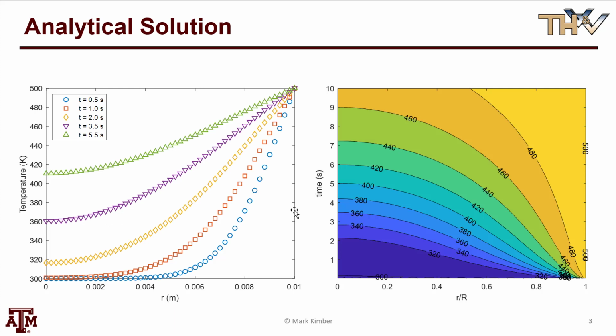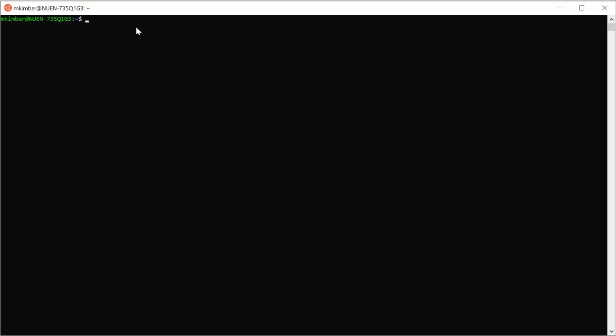So how do we do this in OpenFOAM? The boundary condition that we are going to take advantage of is called a wedge boundary condition. And what that means is I'm taking that cylinder and taking a wedge slice of it along the length of the cylinder.